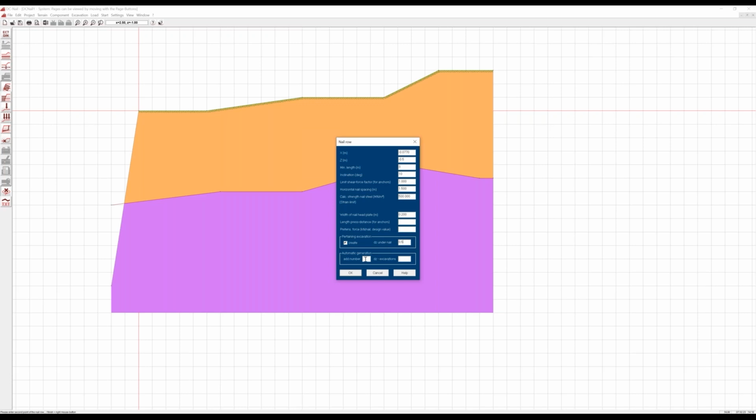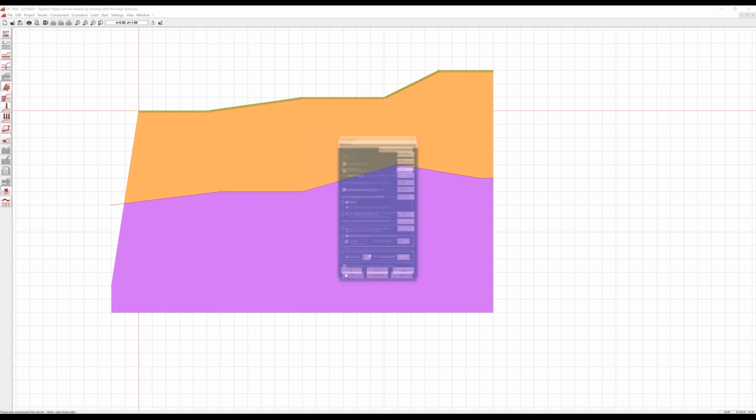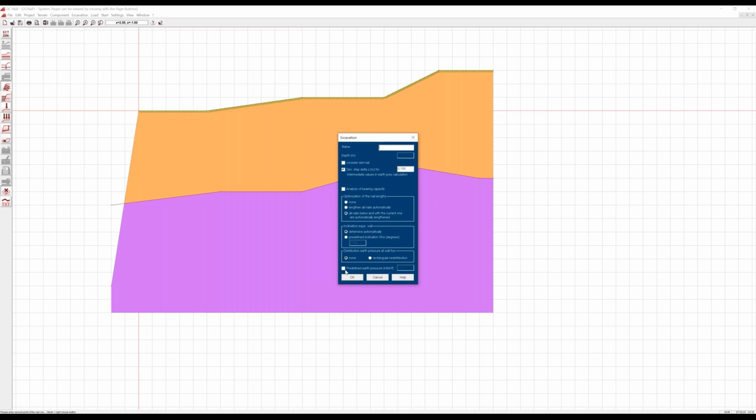And I want to have, for example, 6 additional excavation stages, all with a difference of 1 meter in depth below the last one. So if I enter these options here, the program asks for the parameters of the excavation. For example, E1 is the first one.